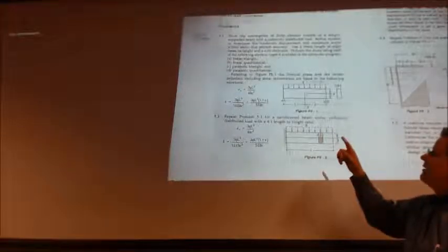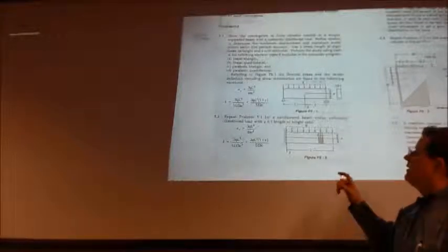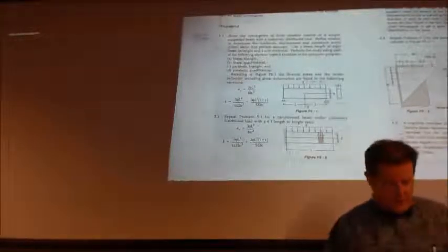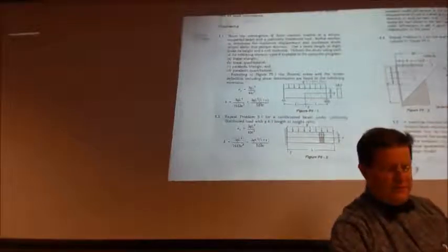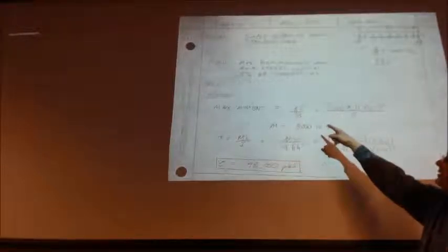The amount of stress that we have, that equation probably doesn't look real familiar or like anything we have in the back of the book. So if we start out with what we know, we can look up for a simply supported beam with distributed weight, the max moment, the equation for determining the max moment is that.